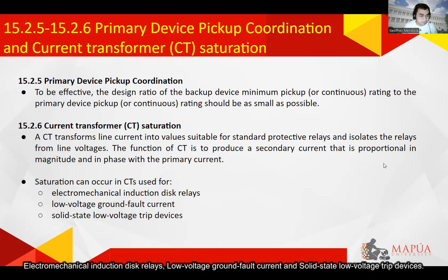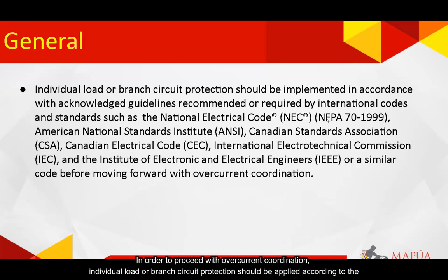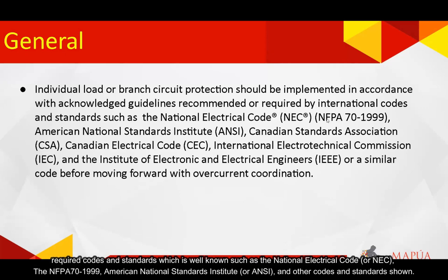So moving forward to overcurrent protection guidelines, in order to proceed with overcurrent coordination, individual load or branch circuit protection should be applied according to the required codes and standards, which is well known as the National Electrical Code or NEC, the NFPA 70-1999, American National Standards Institute or ANSI, and other codes and standards shown.